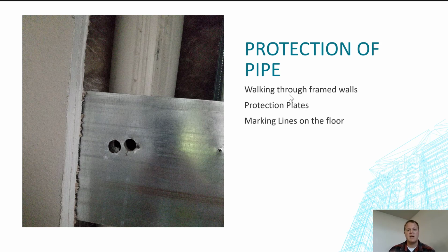And a lot of times it damages the piping, or you get nicks and scratches on the piping, or you snag your foot on the piping, crack it, whatever. Same thing with electrical. It can damage your wiring as well. Protection plates are a big deal. So if you had a stud, anyway, I think protection plates. If you don't know what that is, Google it real quick.